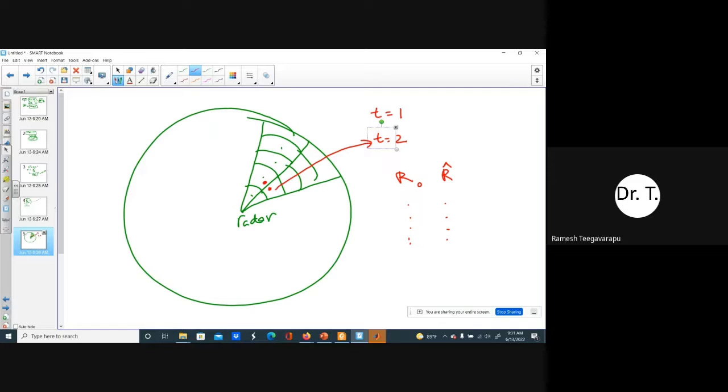But of course, rain gauges, if you have a recording rain gauge, you might have a rainfall available instantaneously, in the sense they are not available at regular intervals. So you need to sum them up to get to a particular interval. And then you have to do the same thing with respect to the radar also. So what radar does is, radar will provide you a set of reflectivity values, Z1, Z2, Z3, Z4, Z5. Let's say this is your 15-minute period.